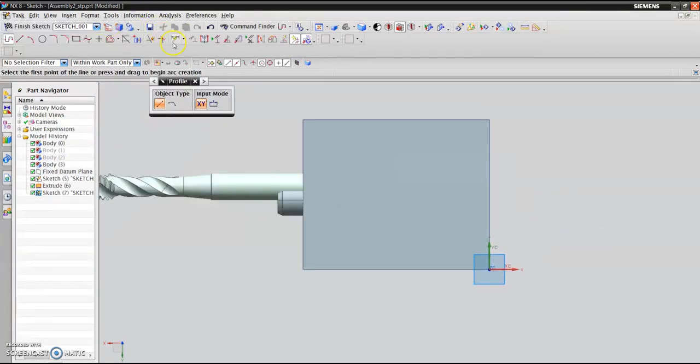So I'm going to draw a sketch, circle, cancel this. Let's create a metric 8mm thread. So 8mm by 1.25, where 1.25 is the pitch. M10 by 1.25 and M12 by 1.75. The second number is always the pitch.